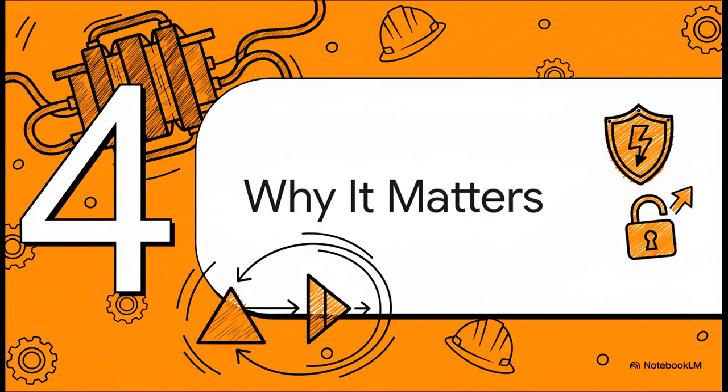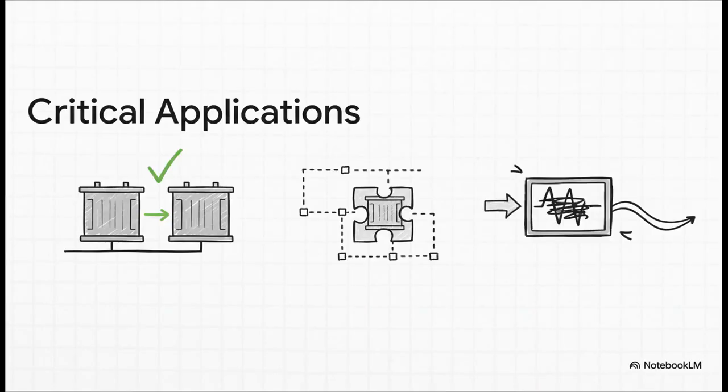So this is a neat party trick for engineers, but why does any of this actually matter in the real world? Why is this code so important that it's printed on every single three-phase transformer? Well, it turns out it's absolutely critical for safety and for the reliability of the whole system. Understanding vector groups is essential for a few key reasons. First and foremost, it's for safely connecting two transformers in parallel to share a really heavy electrical load. It's also vital for making sure different parts of a power system can actually work together. And it even helps manage nasty electrical noise, which we call harmonic currents, that can mess with sensitive equipment.